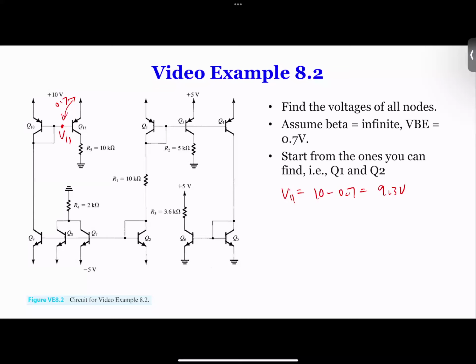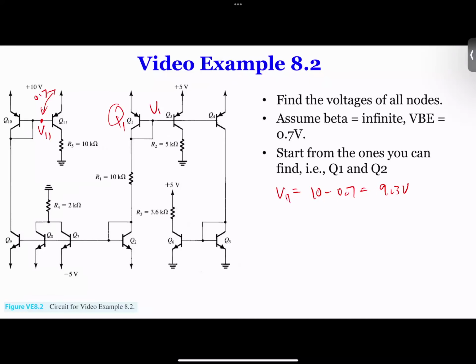And then we want to calculate the current, but the problem is that we don't know what V is here. So again, okay, we got stuck again. I looked at the wrong Q, so Q1 is actually here. The reason that we can find Q1 is, again, 17.5 volts minus 0.7, we'll find the voltage over here. So let's go to V1. So V1 is 10 minus 0.7, 9.3 volts, right?